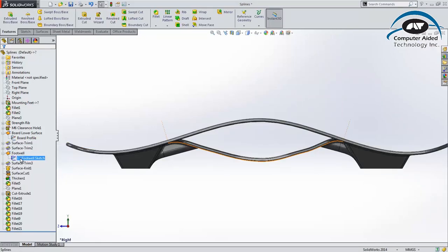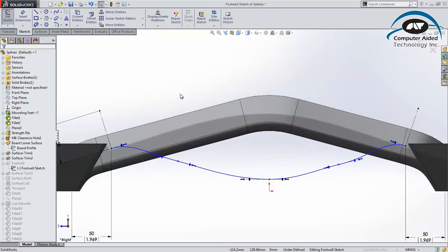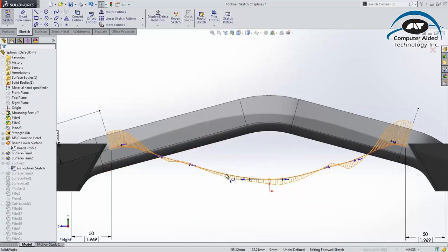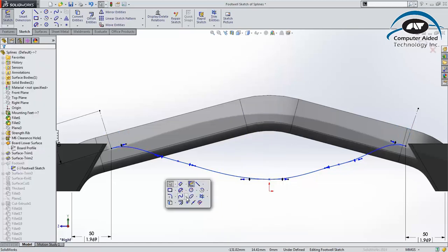Finally, while we're talking about splines, sometimes, especially for new users, they can be intimidating trying to get all the geometry just right. Controlling the inflection and maintaining a smooth profile require proper definition of spline points, such as this spline here. SolidWorks 2014 introduces a completely new spline tool that removes all of these concerns, called the style spline.